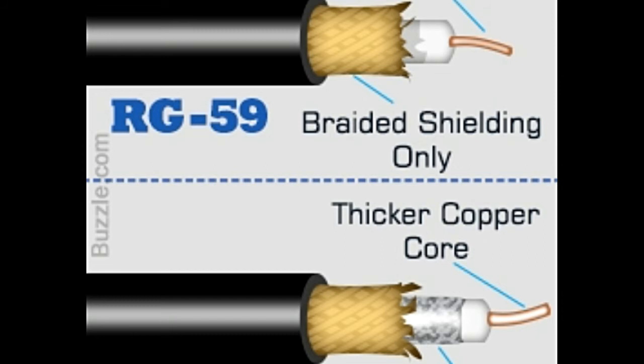However, the RG59 cable has a 22 American wire gauge center of multiple strands of wire, while the RG6 cable has an 18 American wire gauge center with a solid copper core. This means that the RG59 cable is smaller in diameter than the RG6. Further, RG6 cables can have additional foil and wire braid shields along with thicker dielectrics, which reduce the flexibility, lessen the degradation of signals, and are able to carry such signals for longer distances.